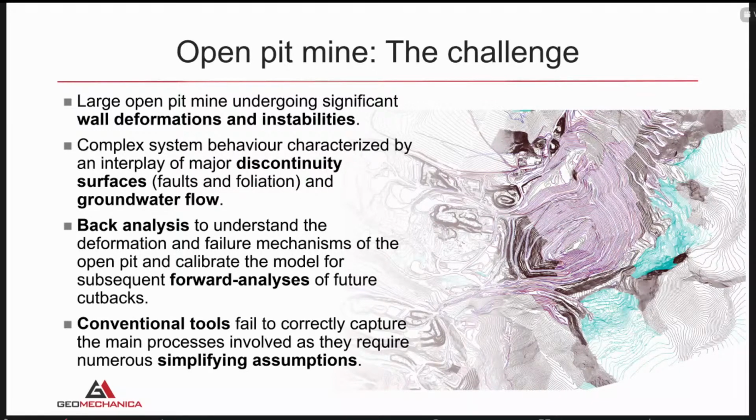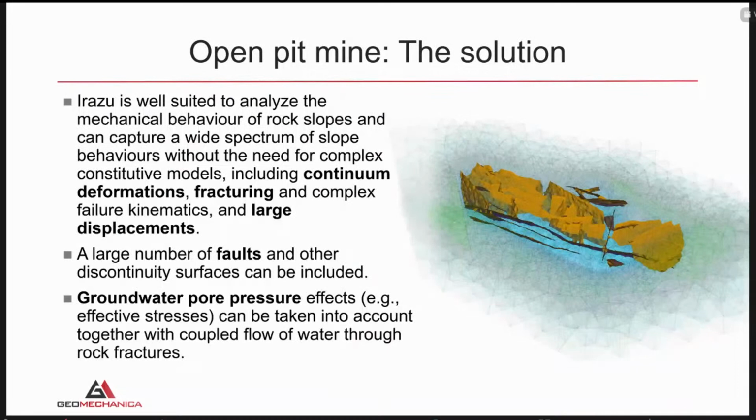We used Irazu, which is well suited to analyze the mechanical behavior of rock slopes. Irazu allows us to capture a wider spectrum of slope behaviors without the need for complex constitutive models. So we could very easily capture continuum deformations, fracturing, complex kinematics, and large displacements.